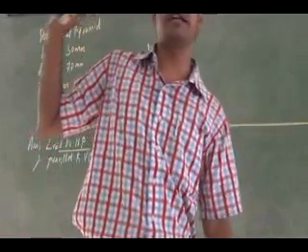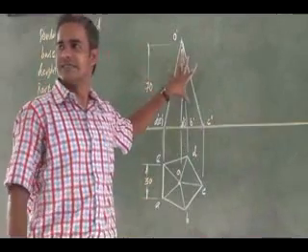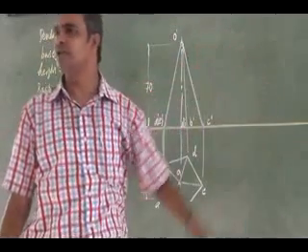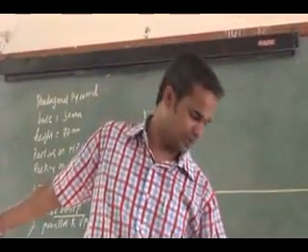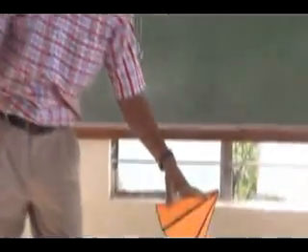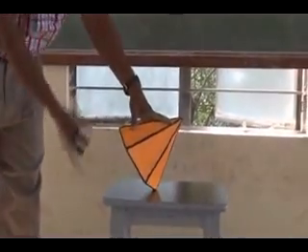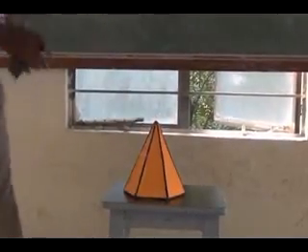By the change of position method, I now have to change this front view to the tilted orientation, that is, the base is inclined 50 degrees to HP. So it is resting with a corner like this. I can just tilt it, so the base I can tilt.